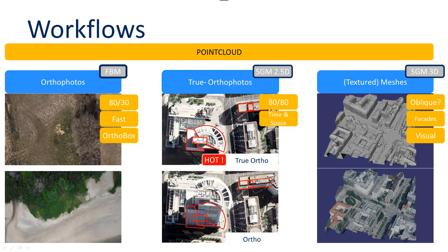with the classic orthophoto you are using a digital terrain model, so our terrain will then be on the ground, and if my projection center is not perfectly just over the building, but a little bit to the left, right, upper or downside, then the building is leaning into our orthophoto, and therefore we are losing content. So we are not able to see here into the streets. We are also not able to see here on the street, and therefore we cannot extract information from the pathway or here from this vegetation behind the building. So these things will then get lost in a classic orthophoto.